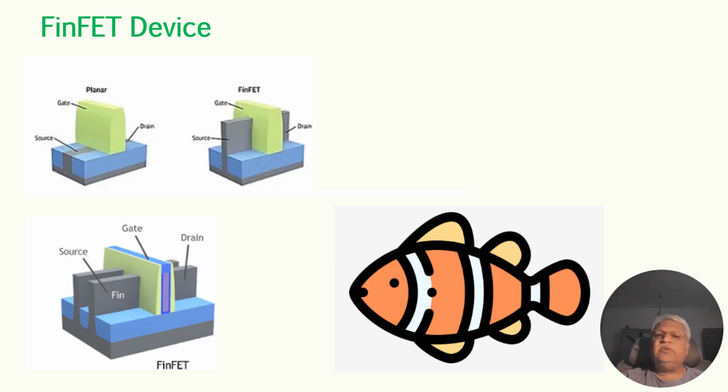If you see earlier, we have known that the channel length is not reducing drastically, but aside to that, there are so many critical parameters like gate length, gate pitch, fin width, fin height, fin pitch, contact size, contact pitch, or metal pitch. All these things are also very key.